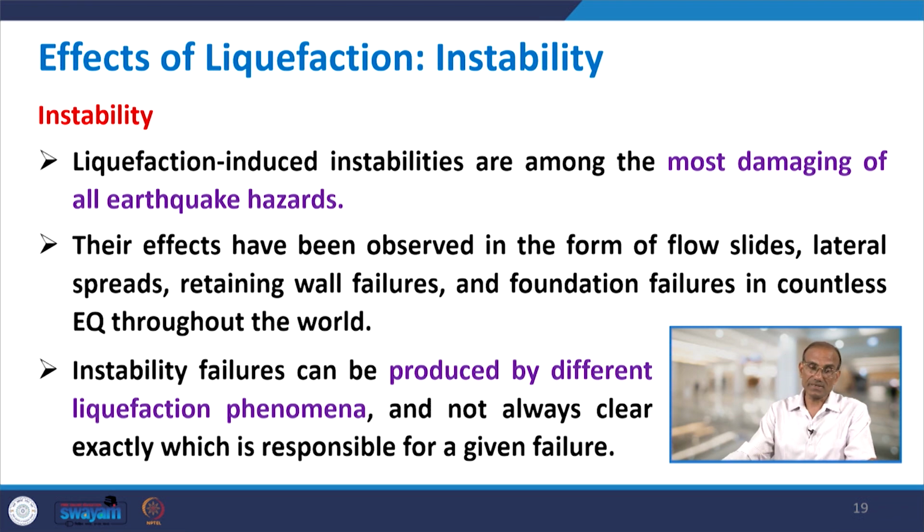Now, coming to the next part, that is instability, and this instability is caused by the liquefaction of the soils. Liquefaction induced instabilities are among the most damaging of earthquake hazards. So, during an earthquake, if there is a liquefaction induced instability, that will cause a lot of damage. Their effects have been observed in the form of flow slides, lateral spreads, retaining wall failures and foundation failures in countless earthquakes throughout the world. So, the effect has been observed; it is well known, the effects of the instability are known.